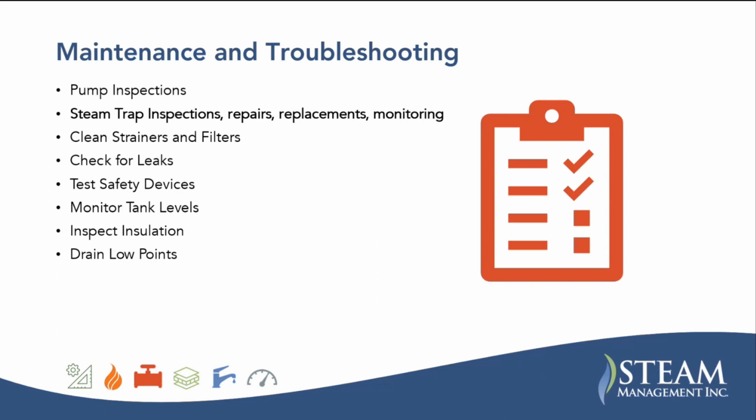Maintenance and troubleshooting. Here's the list of different things that come up when you're performing maintenance, and we'll talk about some of these. But pump inspections is a big one. We're talking about condensate pump inspections, whether they're mechanical or pressure motive pumps. The pressure motive ones are the ones where it's a little less obvious that they're not functioning, and we'll talk about that on the next slide.